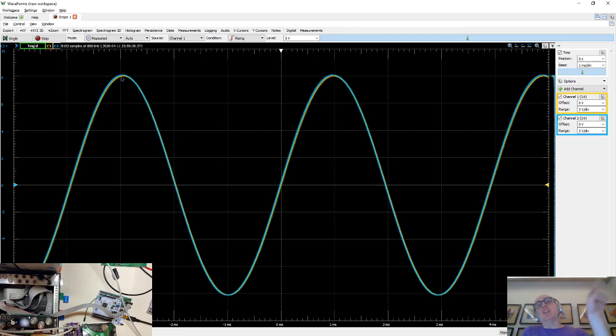So basically, if you remember, I'm filling in a single buffer and it's left, right, left, right, left, right, but I just wrote it lazily as a single sine wave. So basically, the left channel is one sample ahead of the right channel. Now we set it to 32 kilohertz, and it's a 128 sample buffer. What is it? 32,000 samples a second divided by 128. So it's about 250 hertz.